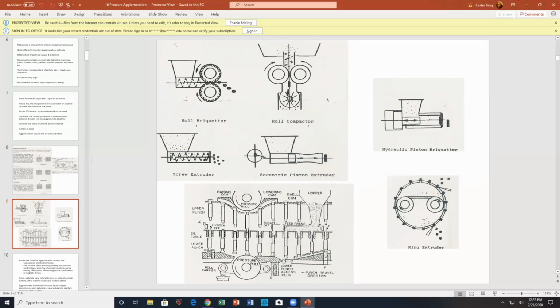You have your famous extruder. Generally, you should recognize the extruder does not mix very well. A twin screw extruder will mix, but a single screw won't. So if you're using it as a mixing device and you're getting poor mixing from it, well, that's understood. It's not a very good mixer. Then we have a 2-roll mill or 3-roll mill here. We have a pellet material.